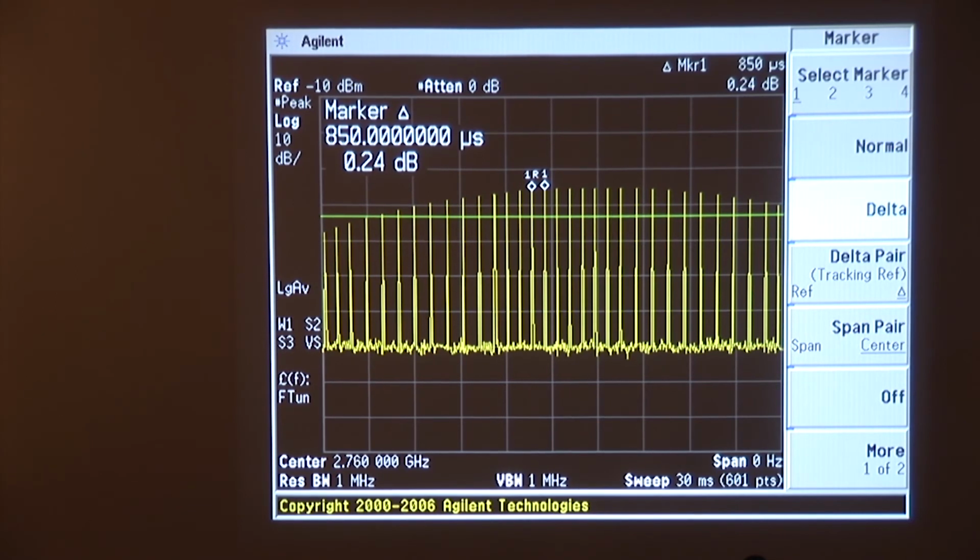This is a problem if you're doing Doppler processing. In order to defeat or prevent those lines from occurring, you have to break up the intervals between the pulses such that the intervals between sets or pairs of pulses are not equal to each other and they're not even multiples of each other. And this is a technique that is used in air traffic control radars, which have so-called moving target indicator processing, which is Doppler processing. So the fact that this radar has stagger evident in the pulse sequence means that, again, it has moving target indicator, that is to say it's got Doppler processing. It's probably an air traffic control type radar because they're worried about using it to get velocities.